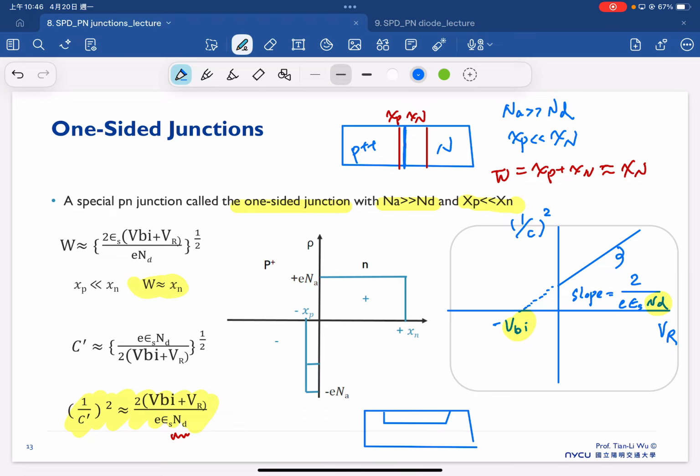But sometimes their information might not be correct. So to double make sure that the doping concentration is correct, we also need to have a very special test key on our chip to measure the doping concentration, because if the doping concentration goes wrong, that will create many issues for the whole semiconductor device.